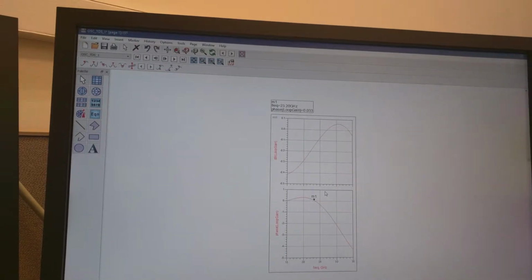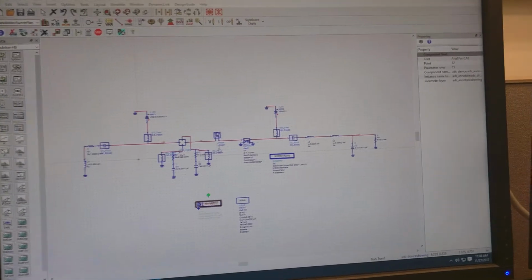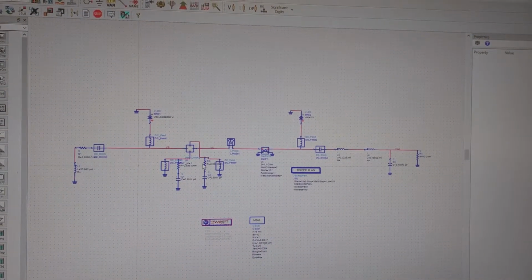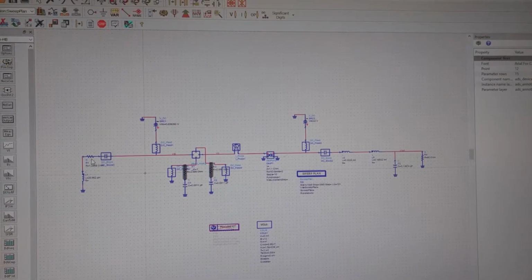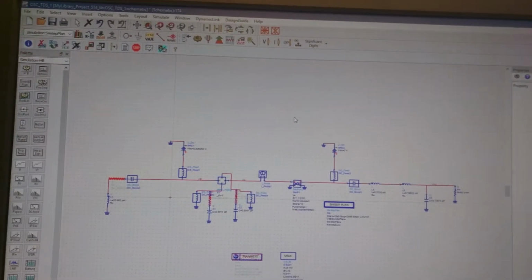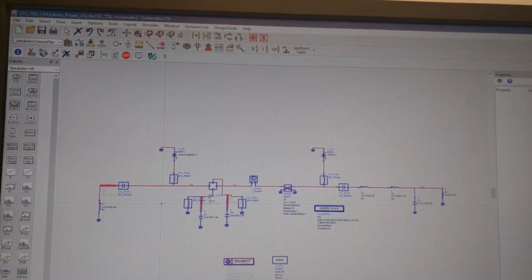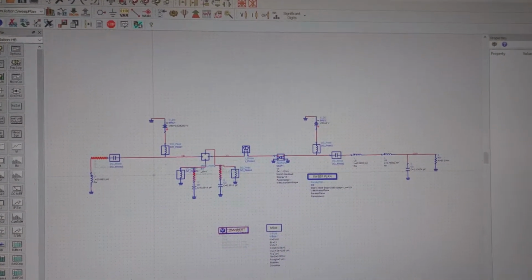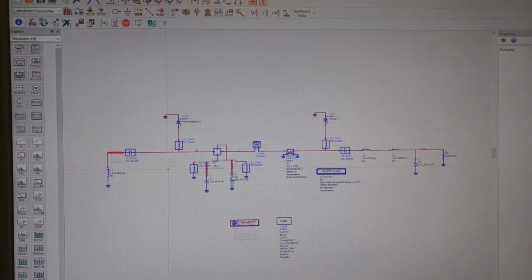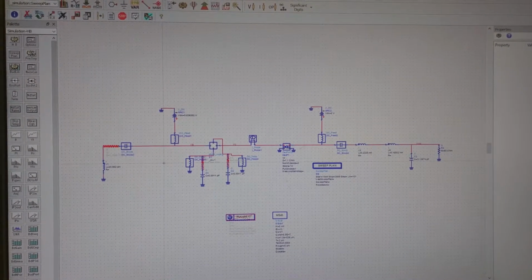Now what we need to do is reduce some loss in the design. To reduce the loss, I'm going to short out these resistors in the feedback and the termination. Now remember, by shorting these resistors, the frequency at which this is going to oscillate will change, but at least we'll see if it is going to oscillate or not. By doing the later steps of adding non-ideal pads and components, we can tune the parameters and remove these resistors anyway if it oscillates at this step.